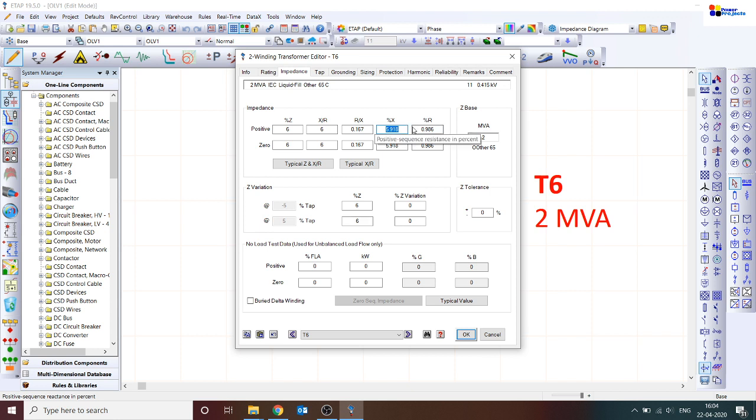X and R will not change in the same proportion. So let's address that question also. Question number 1: do you think that the resistance will change with respect to the frequency? Here we have two terminologies. One is percentage Z, the impedance of the transformer, which is further classified into reactance and resistance. If we have designed this transformer at 50 hertz and are trying to use it at 60 hertz, what will happen to percentage X and what happens to percentage R?